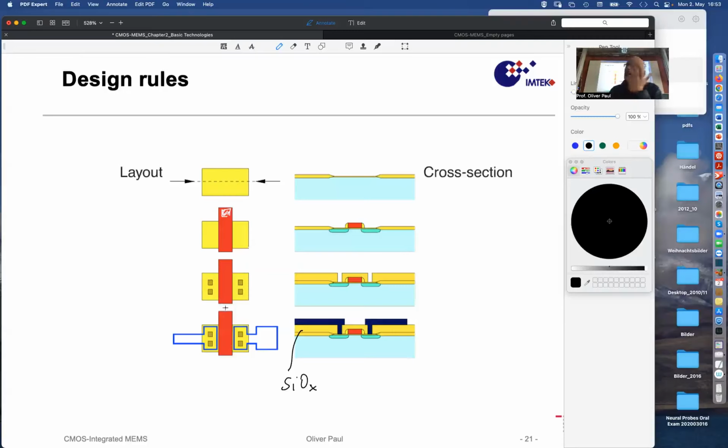And therefore, a technologist will be able to tell you, yeah, per hole, we have a resistance of so much. And then if you have 10 in parallel, you know that the resistance of the 10 in parallel will be 1/10 of a single hole. And this is how circuit designers can design their circuits if they need to implement this level of detail into their circuit simulation. So the next is this metallization deposition.